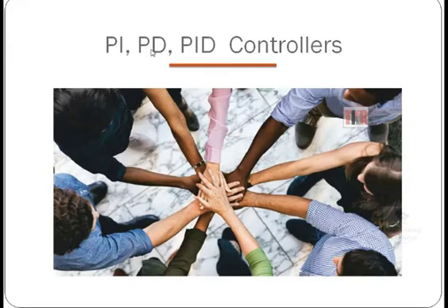See, based upon our previous things, we can decide what we can do. But PD means I don't know the history. I don't know anything about me. Just I want to focus on the future. Is it possible? So compared with PI, PD holds good. But PD is not widely used because just focusing on the future without any past history, it will not be effective, it will not give good predictions. Whereas PID means here I know the present value, I know the past value, and I am able to predict the future. So this will hold good.